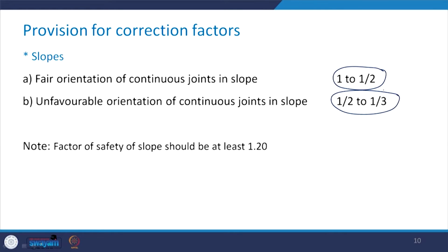Take a note here that in such cases the slope should be stable and its factor of safety should be at least 1.2.